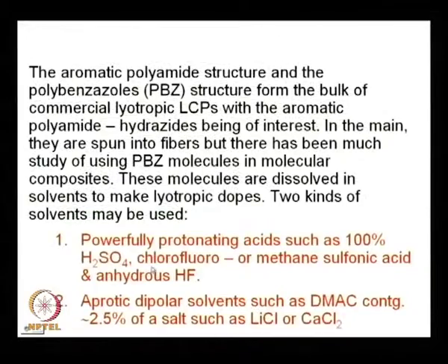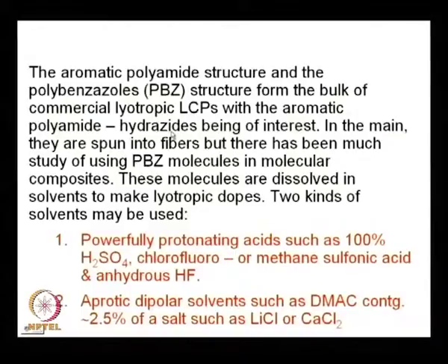What I want to show you actually is that the aromatic polyamide structure and the polybenzazole structure form the bulk of commercial lyotropic LCPs, solution phase liquid crystalline polymers, with the aromatic polyamide hydrazide being of interest. In the main they are spun into fibers, but there has been much study of using polybenzazole molecules in molecular composites. These molecules are dissolved in solvents to make lyotropic dopes. A solution is called a dope. If you put something in a highly viscous system, it is called a dope. A solution of a solute in a solvent is called a dope.